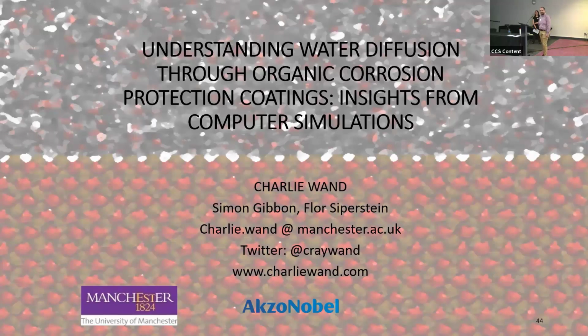One thing that I think is important, as an aside, is that your model, which demonstrated an increase in pore size by increased cross-linking, is something that we have found by over-curing particular types of coatings. They're supposed to be cured after a certain length of time. If we cure them for longer and longer, the coating expands, which was completely unexpected by AkzoNobel. We can physically measure the expansion, and the only answer is that it has increased pore volume, but it has increased corrosion protection. There's more water in there, but it's transporting less.